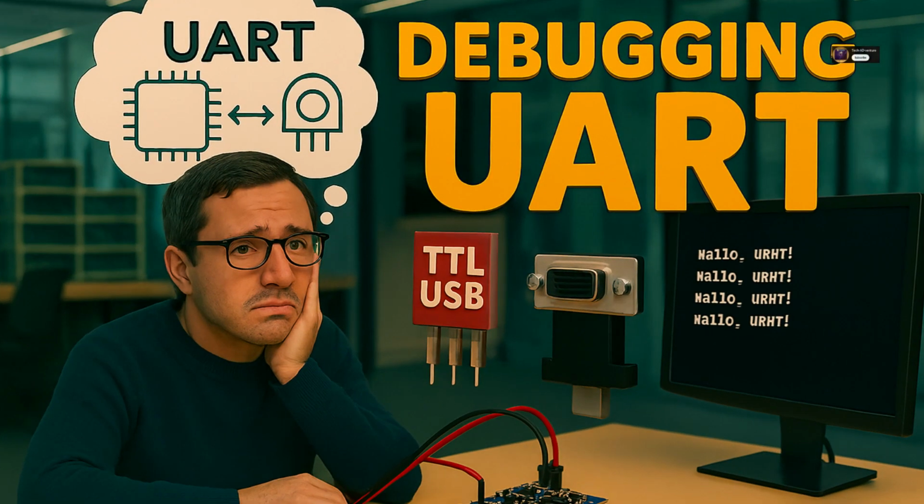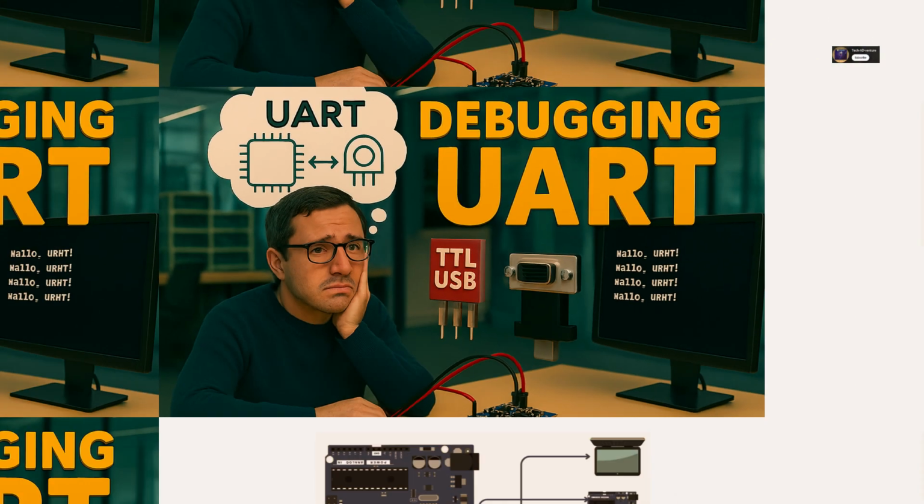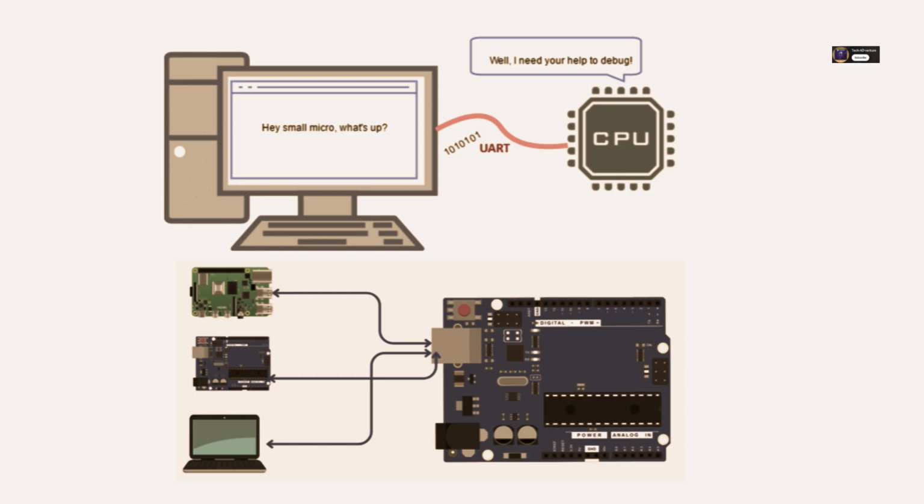Got it. So we know the basics now, but where does this actually show up? What are some everyday applications? Oh, UART is surprisingly common, especially in the embedded world. Debugging is a huge one. If you're writing code for a microcontroller, you'll constantly use UART to send messages, like variable values or status updates, back to your PC. It's how you see what's going on inside.